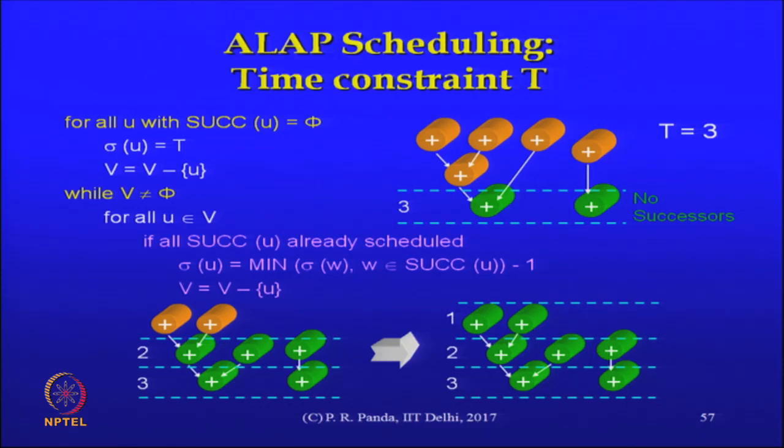What information can we derive from here? These are ideal schedules, remember, they made assumptions that were violating our constraints in terms of availability of resources. But still, what information could be derived from here that is useful? You are scheduling a DFG in a particular cycle, where can you schedule, first cycle or third cycle? Yes, it bounds for us the range in which the schedules of individual nodes can lie.